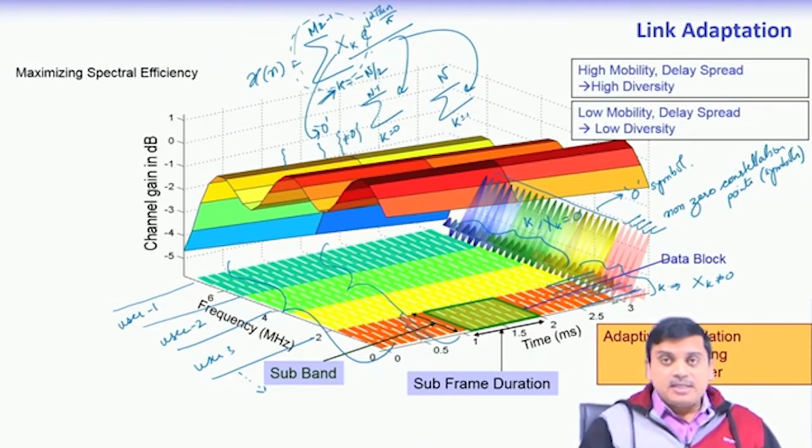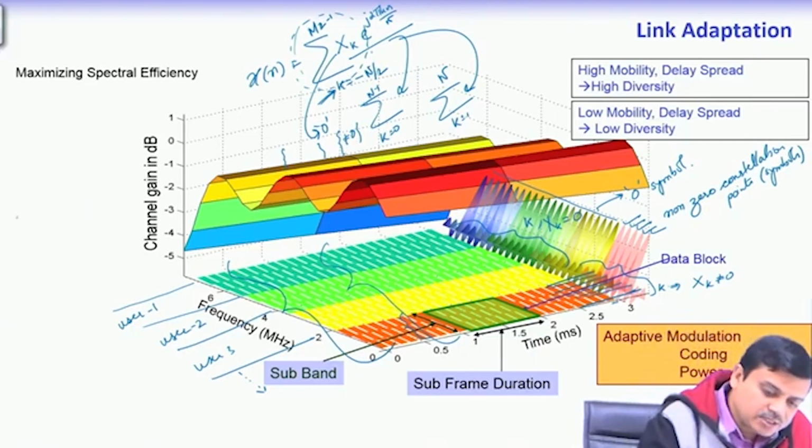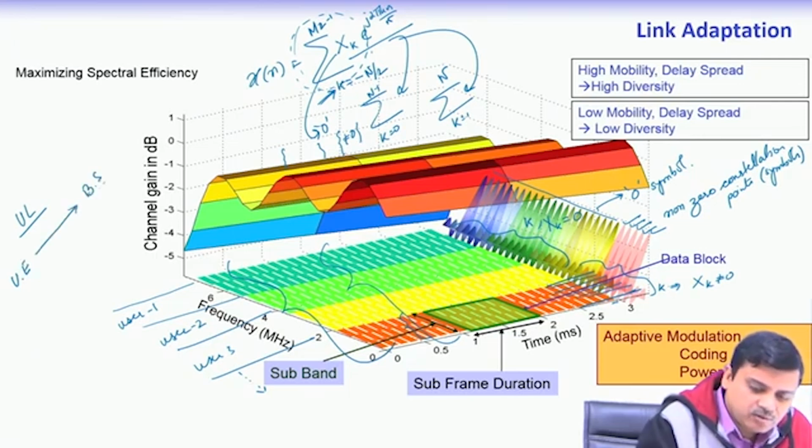So, the base station suffers a PAPR problem, but look at this, we have discussed in the previous class that in the uplink direction the PAPR problem is addressed in LTE, whereas in the downlink it is not addressed. The main reason we have said is that uplink is from the user device, user equipment, to the base station, which is also known as the eNodeB.